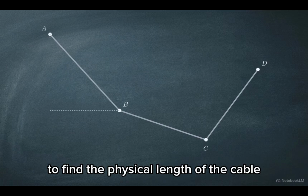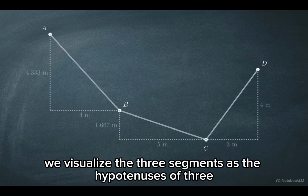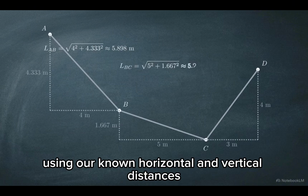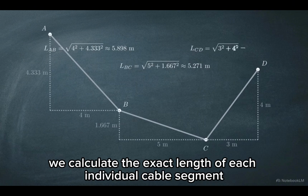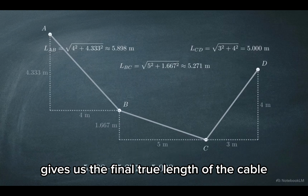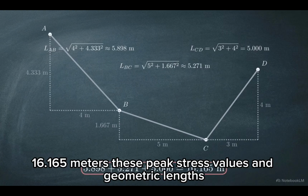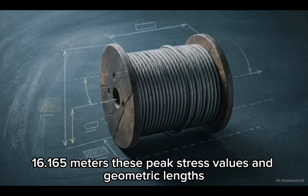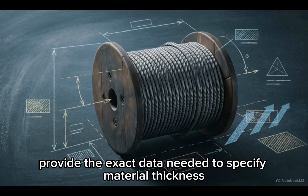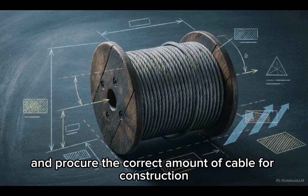To find the physical length of the cable, we visualize the 3 segments as the hypotenuses of 3 independent right-angle triangles. By applying the Pythagorean theorem to each triangle, using our known horizontal and vertical distances, we calculate the exact length of each individual cable segment. Combining those 3 lengths gives us the final true length of the cable, 16.165 meters. These peak stress values and geometric lengths provide the exact data needed to specify material thickness and procure the correct amount of cable for construction.